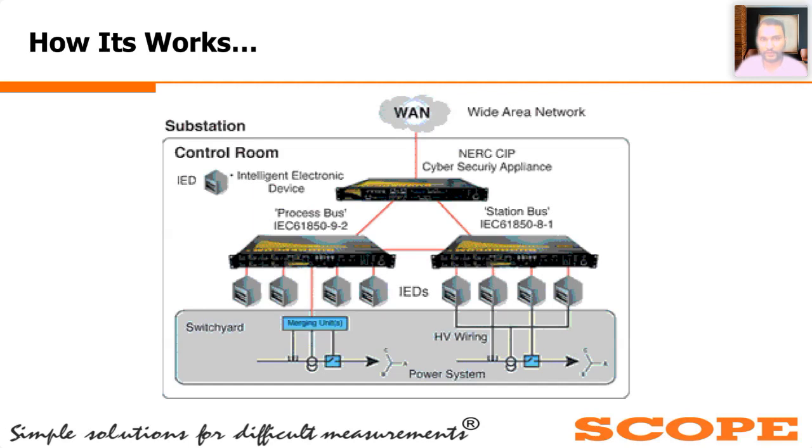From that server, you can visualize your substation parameters on a local SCADA HMI, and you can transmit them to an SLDC or remote control center through a gateway. So this is a typical application where we utilize switches at the station bus level, not at the process bus level.